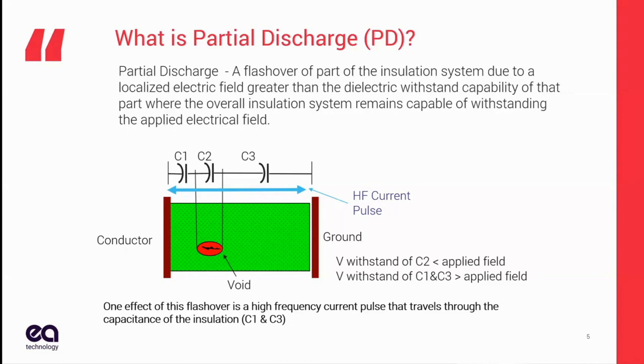If you've done any work in protective relaying for cables, you know that you have to allow for the charging current. That's a 60 hertz, or power system frequency, current going through the capacitance of the insulation. And it can be substantial, it can be a couple amps. So you need to realize that we have this capacitance everywhere, and that's where we have this issue.